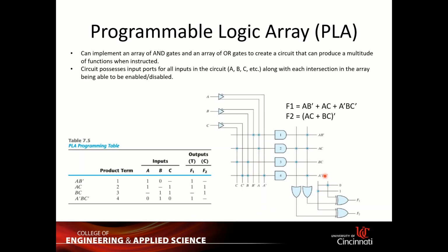So finally, you ask yourself a question. Okay, this is an important question. Now you have kind of the output, right? Now you want to ask yourself, do I want to invert this function or do I want to keep it the same? If you want to invert it, you will link this XOR gate to a 1. If not, you link it to 0.